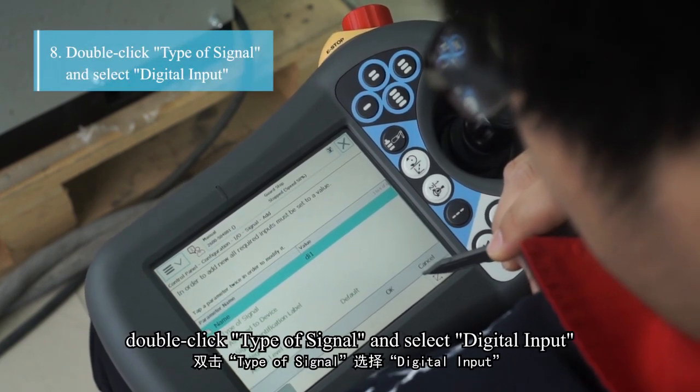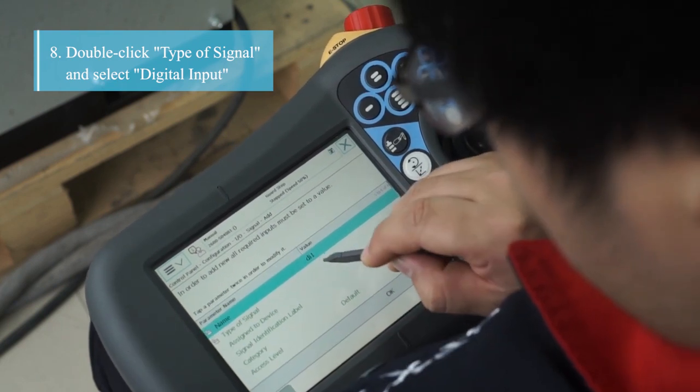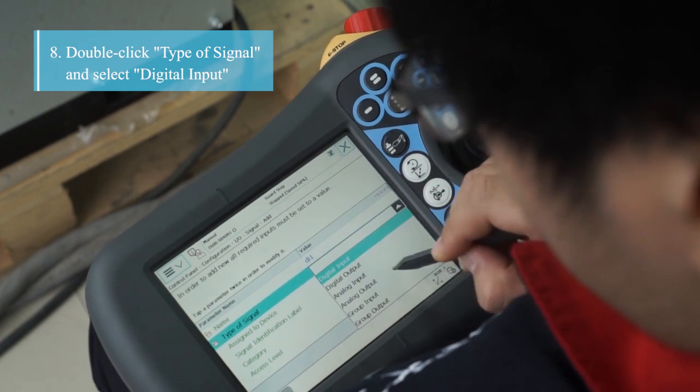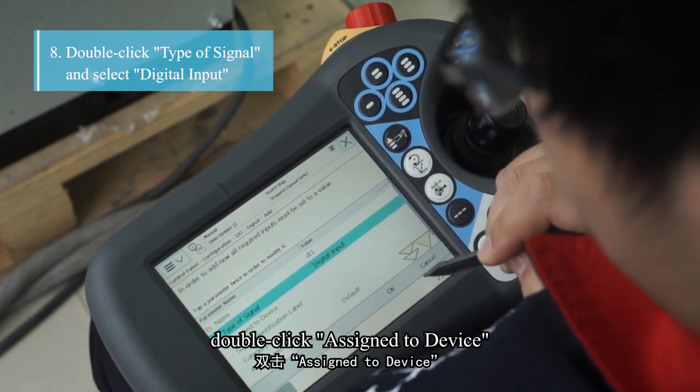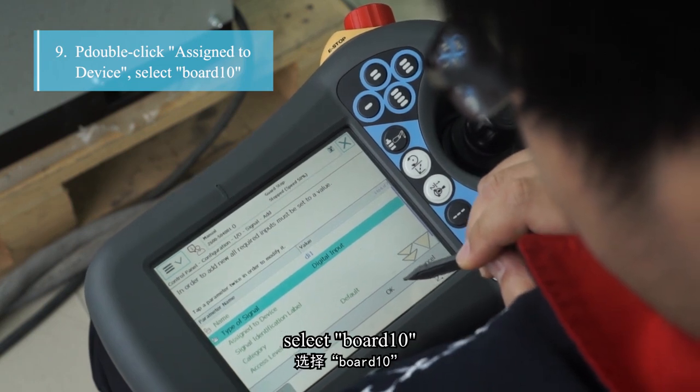Double-click Type of Signal and select Digital Input. Double-click Assigned to Device, select board 10.